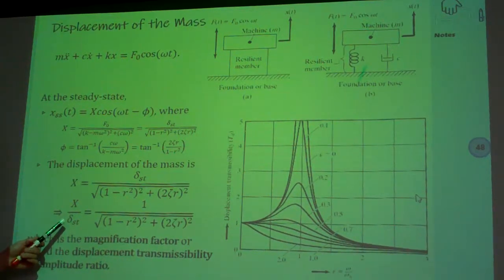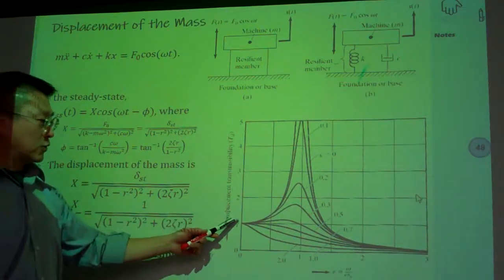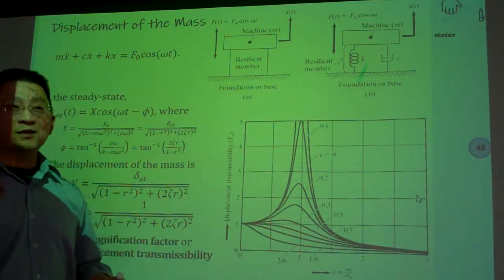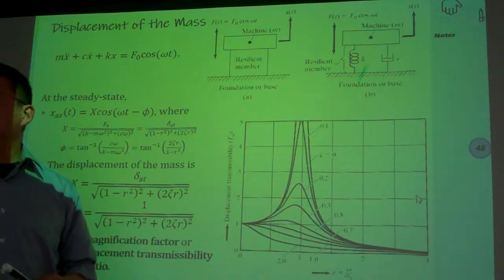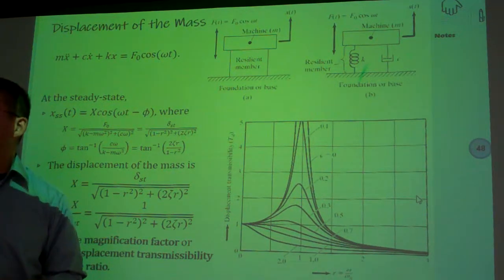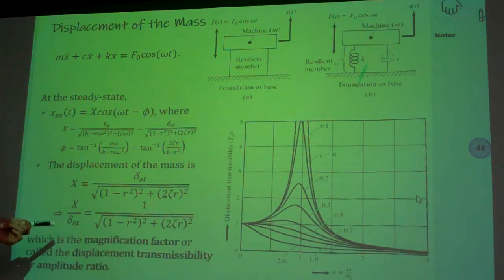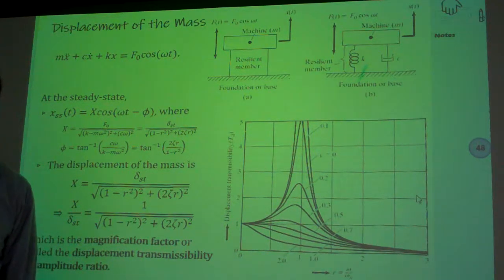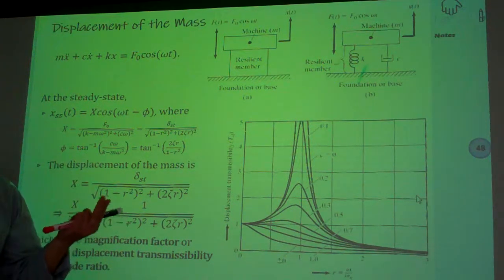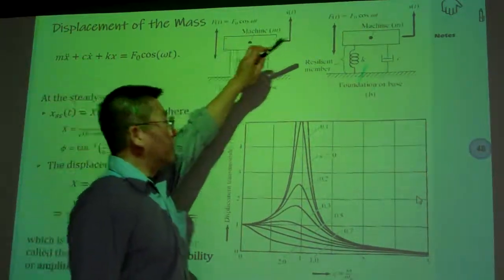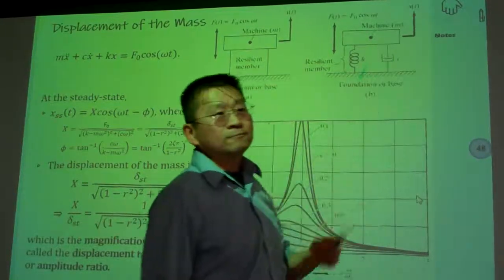In a similar process, once you know the damping ratio to minimize based upon the working range, you simply look at the curve. You can easily pick the point that will give you a good solution. This example is very straightforward, so I don't have examples, but this basically summarizes our design aspects. Good. So keep that in mind: two aspects of the design. One is on the force transmission, and the other is on the displacement transmission. Okay, good.